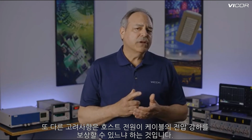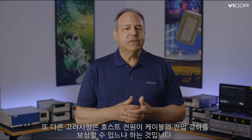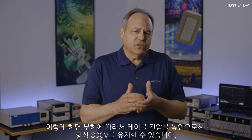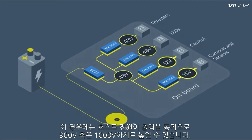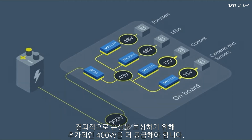Another option to consider is if the host supply has the capability to compensate for the voltage drop. That is, to increase the tether voltage as load increases so as to always have 800 volts at the vehicle. In this scenario, the host supply can dynamically raise its output up to 900 or even 1,000 volts, and as a result needs to supply an additional 400 watts to compensate for losses.